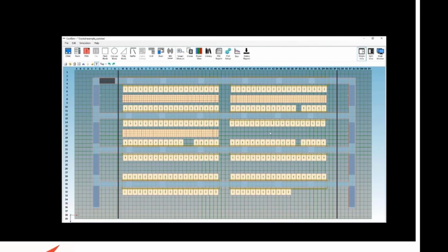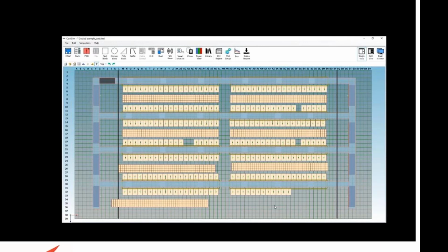So now I'm dumping the heat up into the room, getting it out of the way of the cold air supply. Again, I haven't done full containment because in this case, I didn't want to. Now, often that's because you've got overhead fire suppression that you need to deal with, or you've got cable trays up there that you have to deal with, and full containment is complicated in many of those cases just for that.